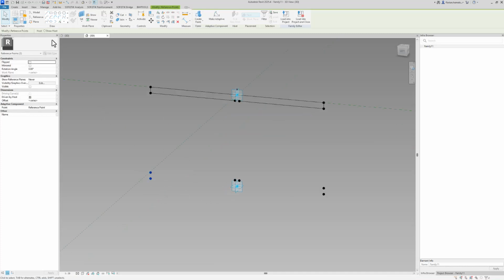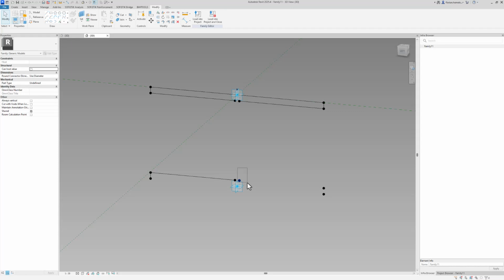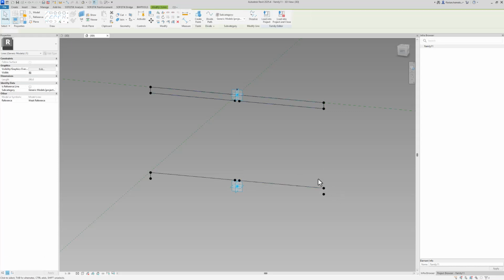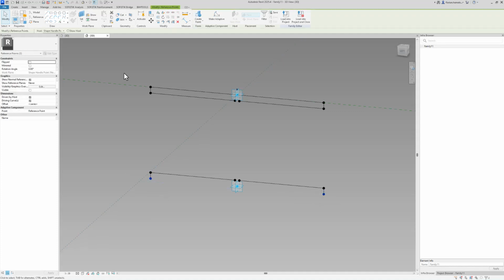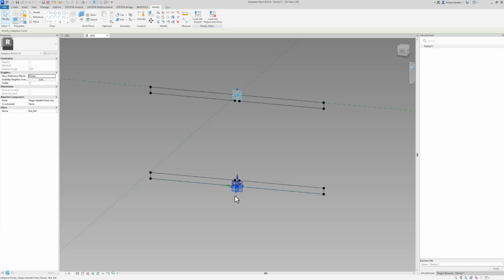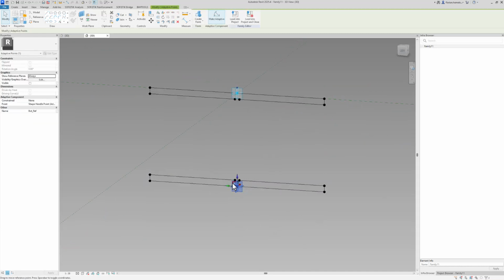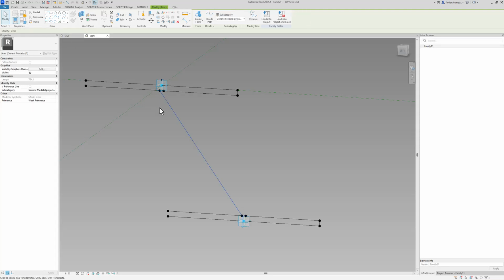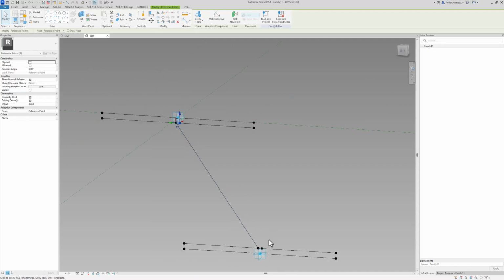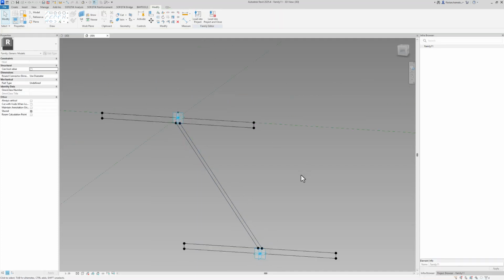I will now connect them together the same way by selecting 2 points and clicking on spline through points. You can see with the selection modus of Revit, it's very easy to connect them together. And the speciality now is that both of them, if I move them in the plane left to right, are freely defining the bottom part and the top part of my flange. I can now select the web points, top and bottom, to create the web definition.